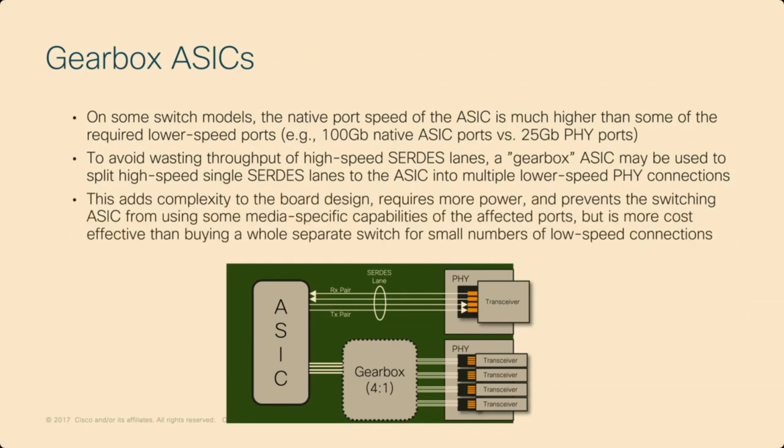So the downside of the gearbox is that it will add a little bit of latency for your signal transmission, and it does increase the amount of power consumed and therefore the amount of cooling required. But it's better if you're trying to have a switch model that has different speeds of connections rather than having to build separate ASICs onto the system for handling the different speeds.